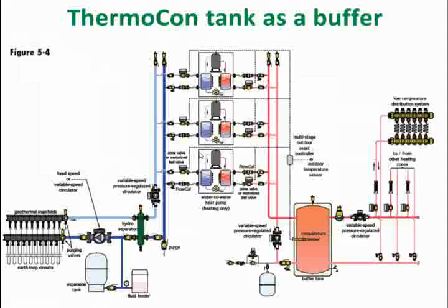Looking pretty good. So we've thrown in a couple more components here on the source side. We put a hydro separator in here so this pump can behave with these pumps here. But now what we've done over on the distribution side is we've put a couple of heat pumps. Now these could be staged in. You know, one heat pump when the load is low, the second one could kick in, the third one can kick in as needed. And also you can sequence these and exercise them. So maybe the first time this one kicks on, the next day this one kicks on. That way you're going to exercise and load them up all evenly so one's not doing all the work there.